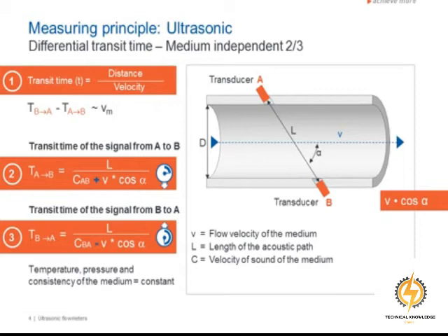In practice, we can assume that since neither the temperature, nor the pressure, nor the composition of the medium will change in these intervals, that is within milliseconds, they remain constant. So, during the transit time period, the velocity of sound can also be seen as constant.